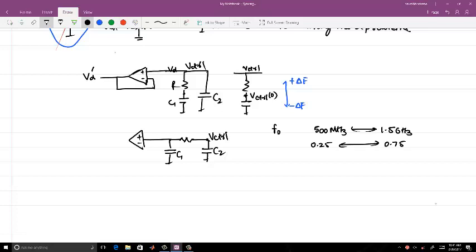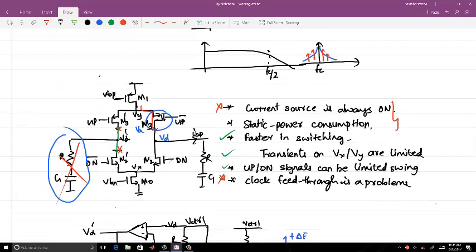So whichever point you pick, your V control will change, right? In a steady state, the V control node has to be this only. And I want to change the PMOS drain voltage of the left hand side, such that I do not see much switching at Vx and Vy transients. So the operating condition should be the same. So we want to fix that.